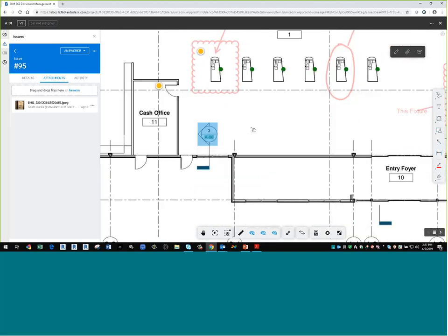Whenever you put a PDF file up, obviously from Revit, the callouts are naturally connected when you upload them. Here, it automatically scanned the drawing, found anything that looked like a callout, and connected it. So it saw right here that there's a sheet called A06. It found that there is a callout type object in the file, so it created a hyperlink to that callout object. So that wasn't anything I had to do, it did it itself natively.